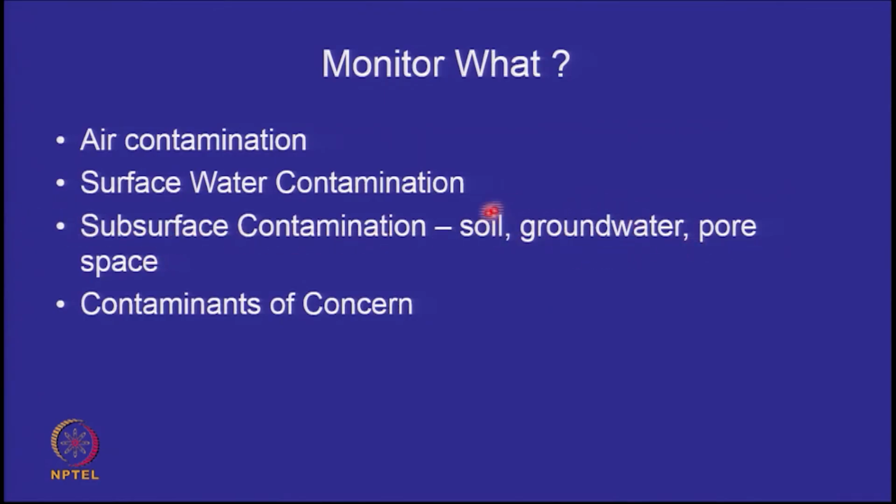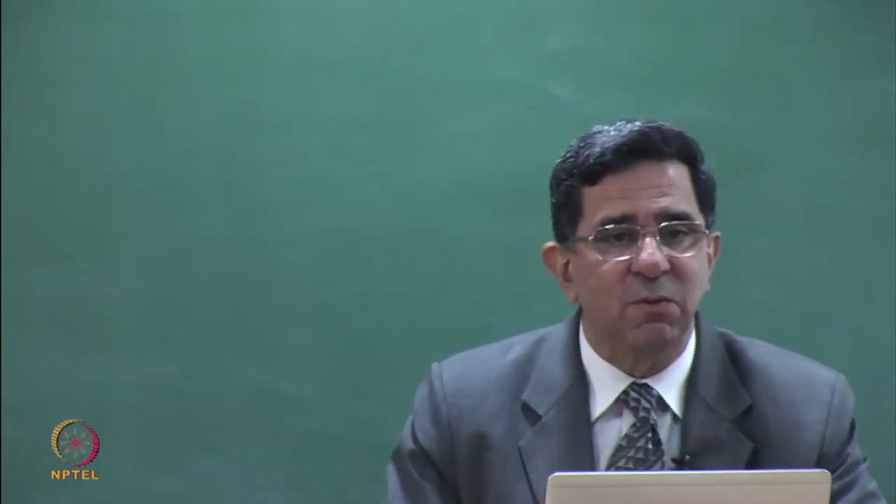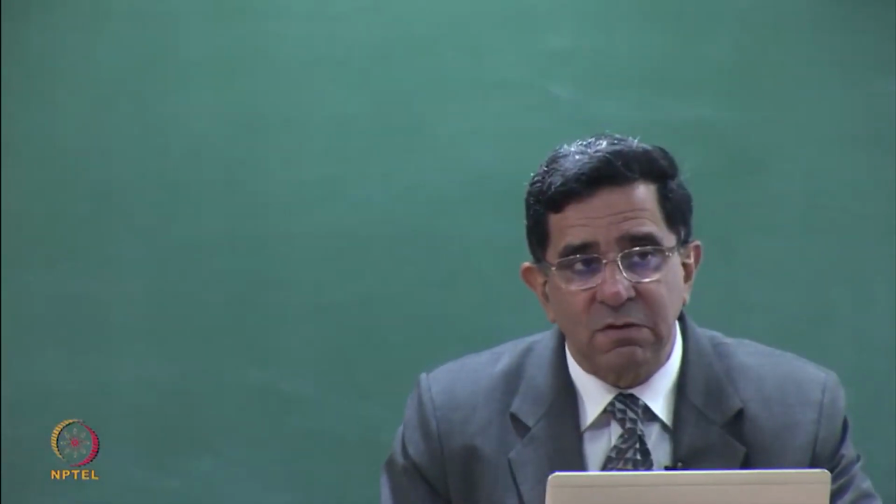It's simpler to monitor the saturated zone because you can extract the groundwater and monitor it easily. And before you undertake any monitoring, you need to understand what are the contaminants of concern. Which is the contaminant you want to monitor? You can't say, I'll monitor this landfill without having pre-specified what is your contaminant of concern.